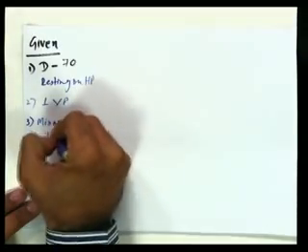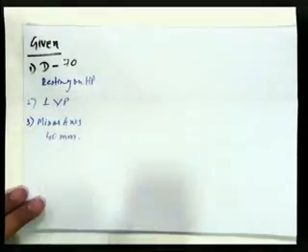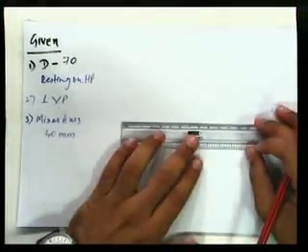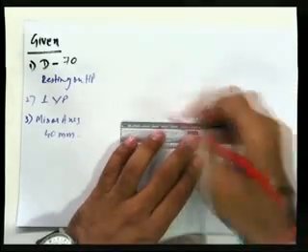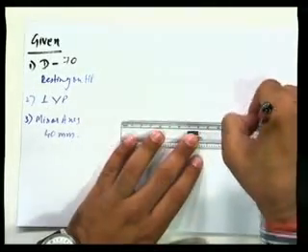as 40 mm. So first of all, we need to actually plot the circular plate on the planes, and then we'll have the general view, the front view and the top view, and then we will draw the exact projection. So let's get on to it. First of all, the first step, as we always do, will be drawing the line XY. A straight line XY.